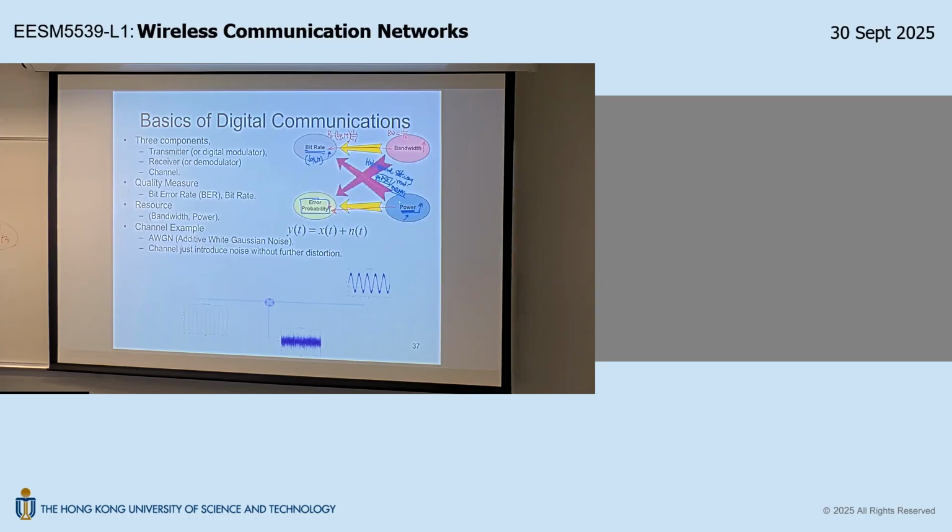Okay. Now, after talking about all this, how is it related to us? We're talking about the comparison between QAM and PSK, right? Now, PSK, by the constellation constraint, is not that efficient compared to QAM, right? Because it only has one freedom. Here you have two freedoms to put 16 points. So this one is more efficient. However, QAM has a disadvantage.